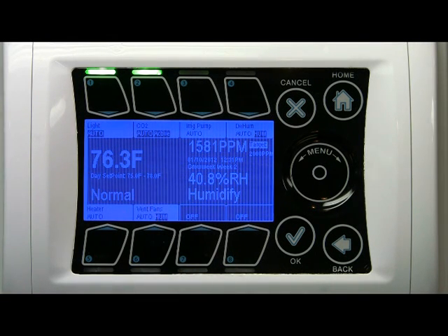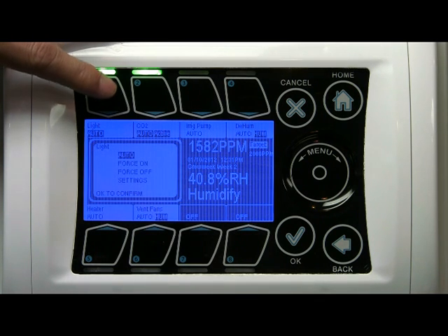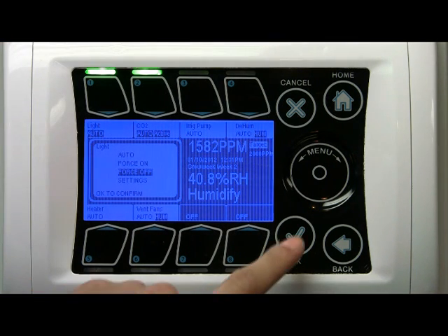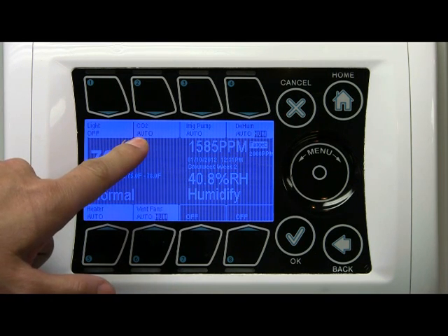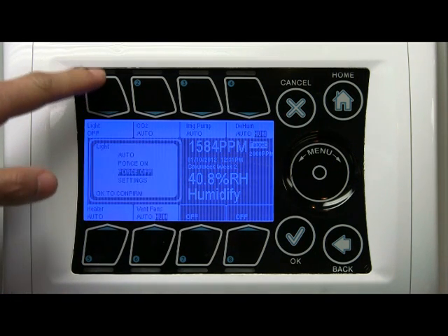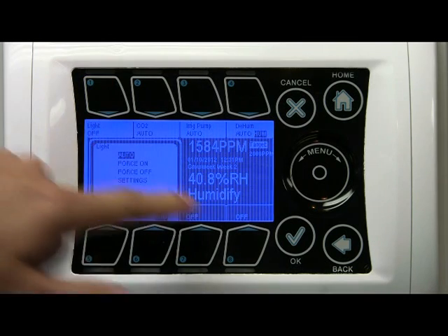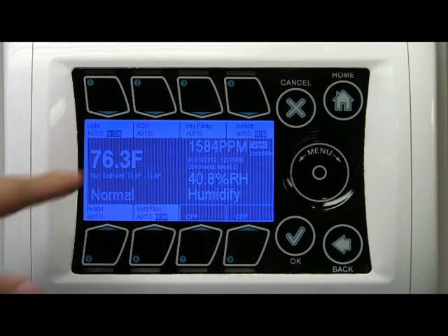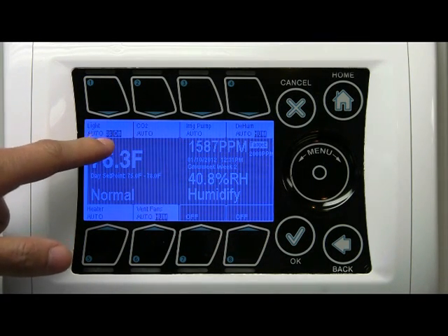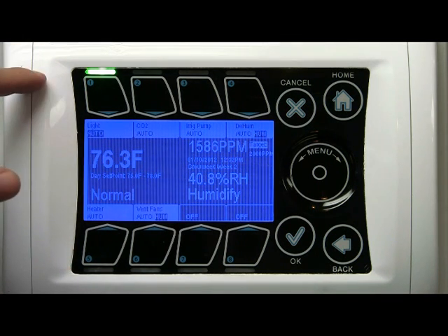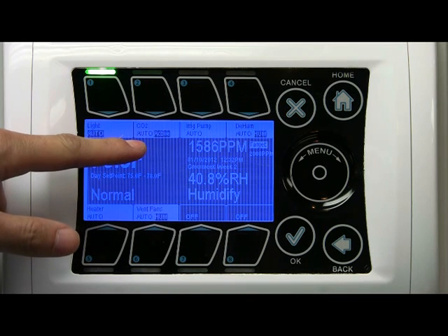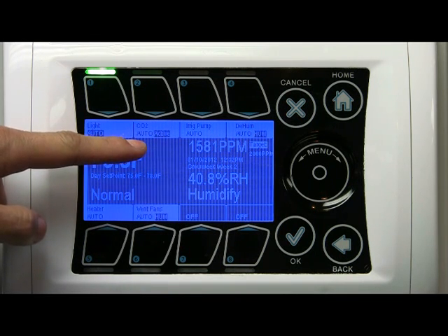But let me show you the light cutoff. So if the light is on, I'm going to force the light off, and you can see the CO2 output gets cut off at the same time. I'm going to allow the light to turn back on again. Again, you see the power cool down timer active here. So once you go down to 0, the light comes on, the CO2 comes back on, being active again.